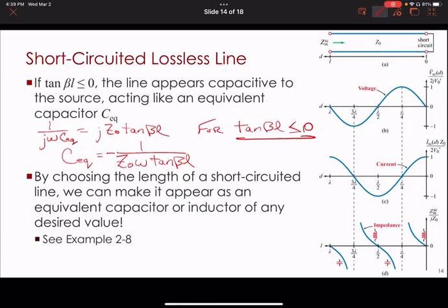You're going to get some leaded ones, meaning the type that you use in the labs. They got these big leads, these big wires off them that you can plug into breadboards. If you broke into your iPad or your phone, you're not going to find a lot of those, right? You can think the whole circuit board isn't that much bigger than one of those big old leaded capacitors or something like that. Then you're going to find tons of surface mount components. Now you're starting to talk a little bit, right? So these are those little guys. If you've looked at any printed circuit boards, you see those little square, cube size, kind of rectangular little guys that are soldered down on each side. And then not only are you going to find one of those, you're going to find those in every size, from decent size ones to some that are so microscopically tiny you can barely see them.